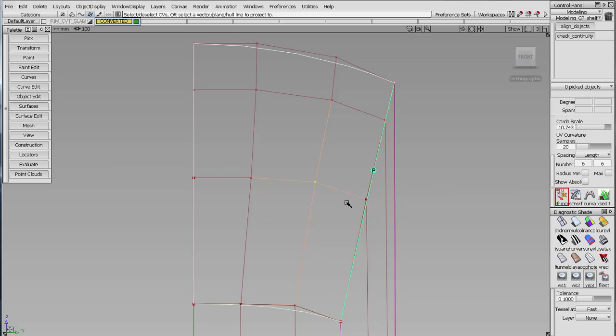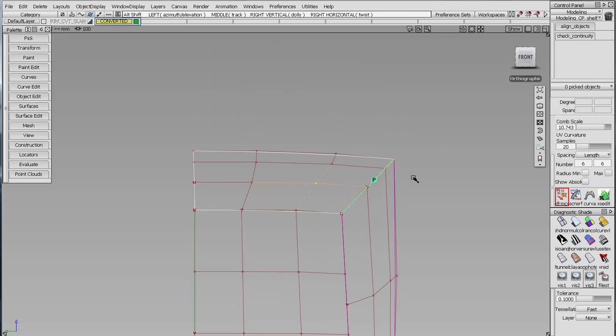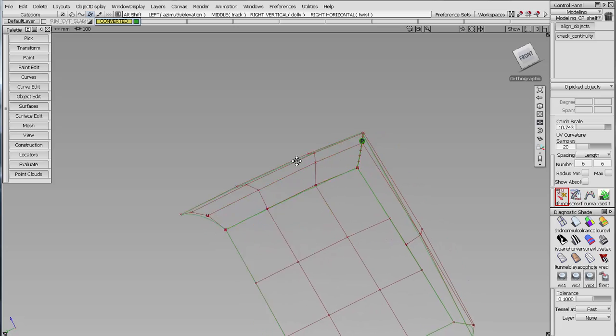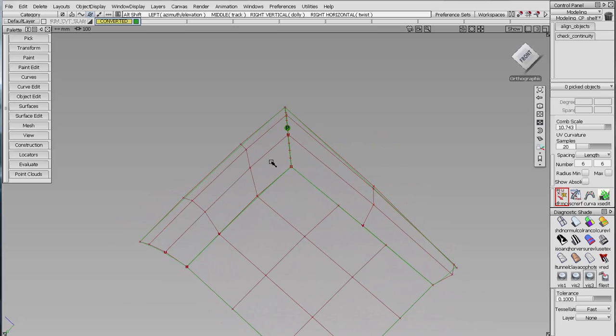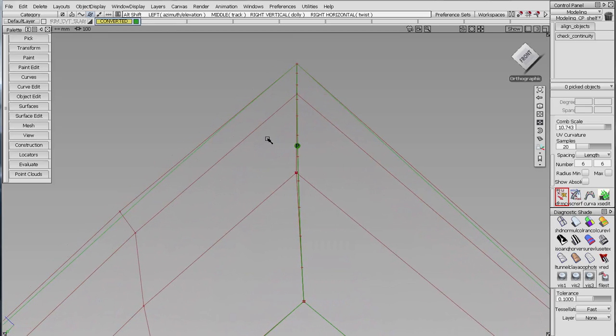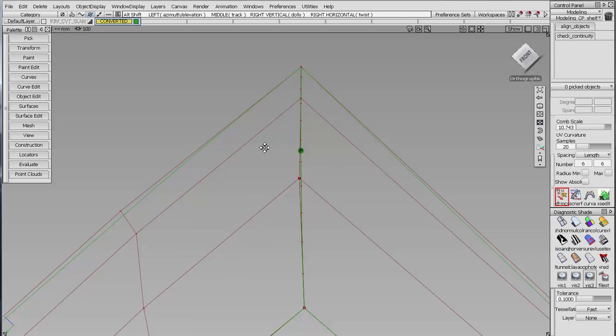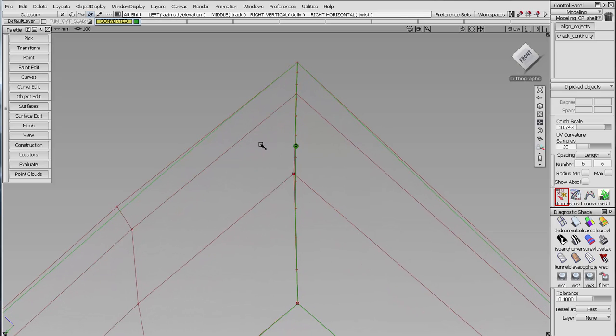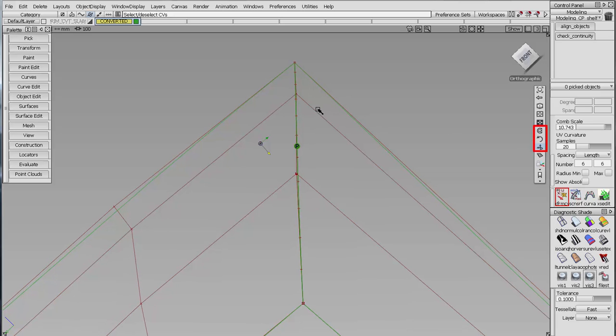But now these control vertices have an ordered structure where it looks like the crown is accelerating out towards the same side, and we're getting a more planar curve in this view. Next, I would turn off my non-proportional scaling view, and I'm going to put this on what I think is a nice flat plane in a view. Okay, so I'm using the right mouse button to twist on the screen, left mouse button to rotate. We can use these twister dials. So now I can pivot right around the top of the screen and get this almost parallel. Okay, so it looks almost straight.